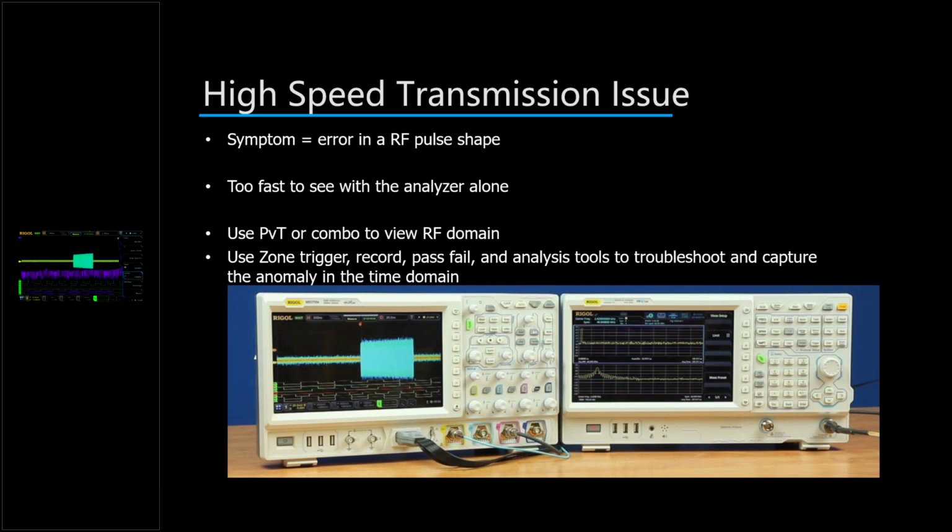So here we'll set our center frequency to 430 megahertz. That's what we're looking at, and our span to about 60 megahertz. So you can see the independent frequency of each pulse. Let's turn on a little peak search there. Turn our threshold down. So you can see the frequency moving across that pattern, and we can see each signal. And then we can record sets of that data as well.